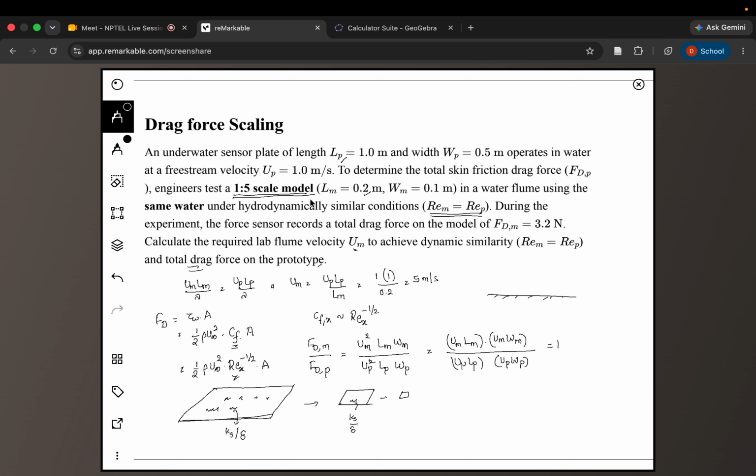So for certain regions, even though these two do not match perfectly with each other, the disturbances caused by these small variations will not grow or cause any deviations in our gross properties like the drag force or, in case of heat transfer, the heat transfer. But beyond a point where this number becomes significantly important, when the surface roughness becomes comparable to the boundary layer thickness, it actually affects the flow, and then your drag force or heat transfer will change.